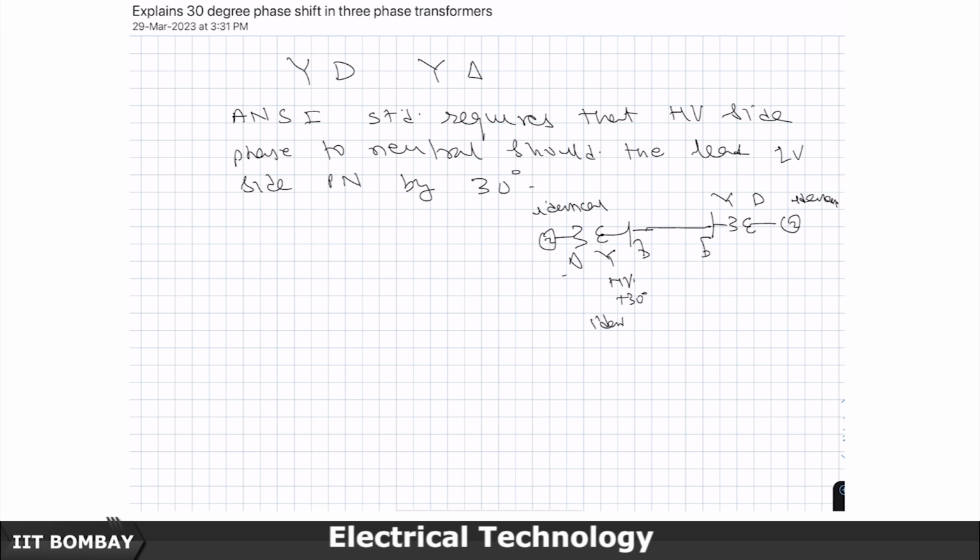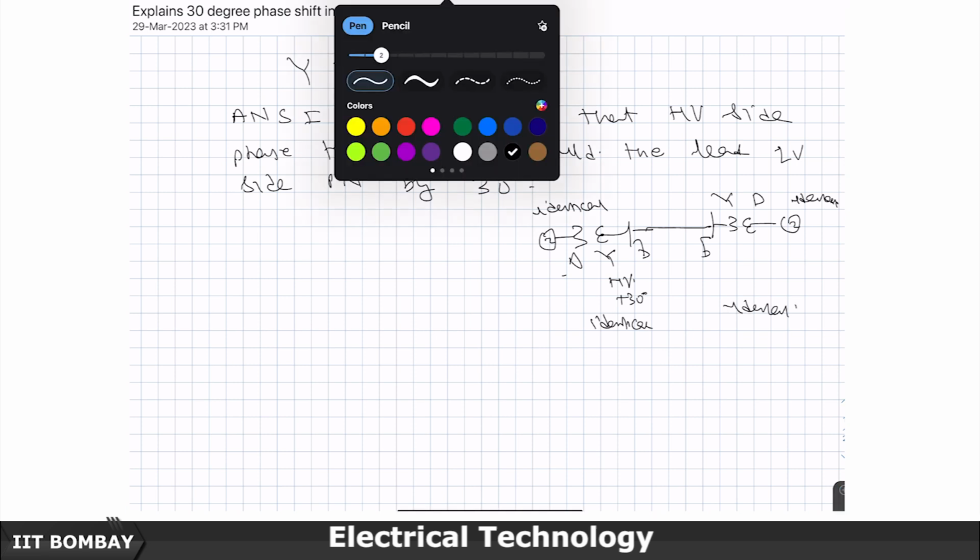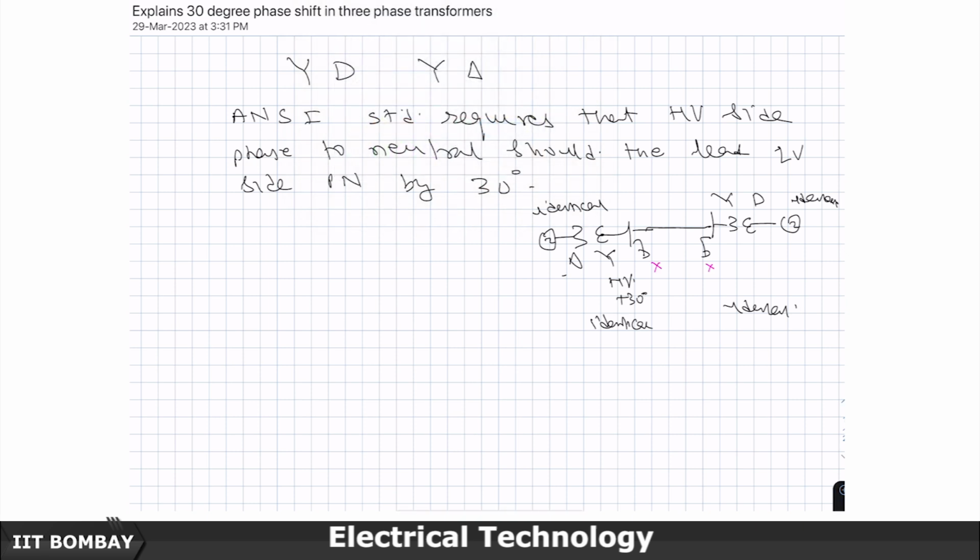The 3-phase transformers are also identical, and if I have not connected any load, then the generator should be running under no load condition, and there should not be any current flowing. And remember the return path, where does it come from? It comes from the grounds which we connect here. So it is not that current does not have a return path; current does have a return path.